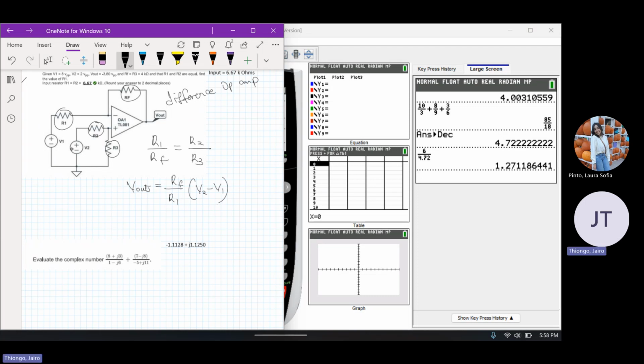So notice it's not V1 minus V2, as one may expect from other problems. That's a tricky part in this question. One way to memorize it would be mostly through multiple practice problems. And also noticing this, that it's the first resistor over the feedback resistor, okay?